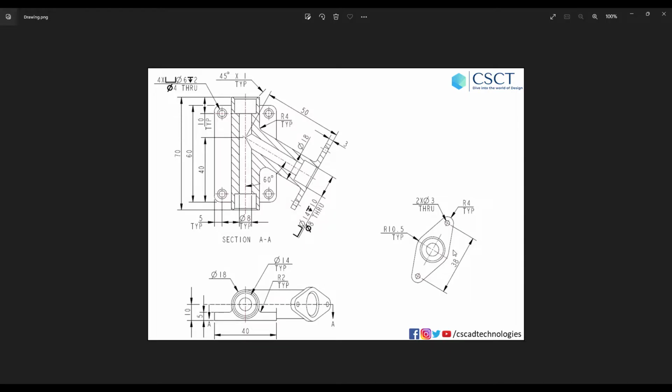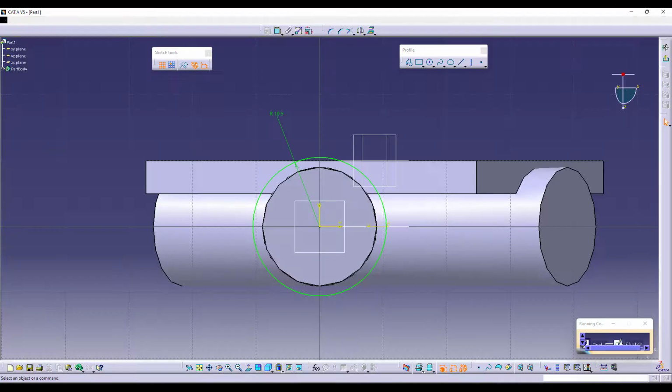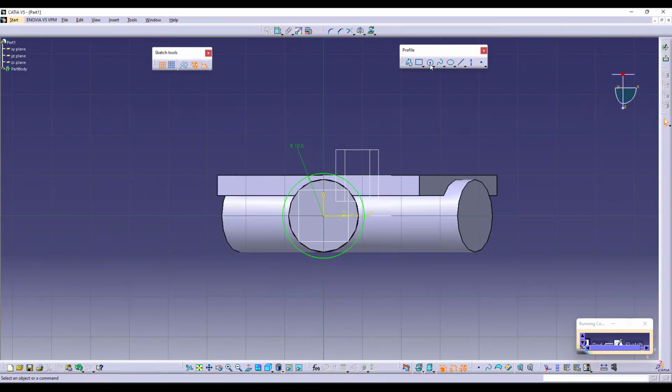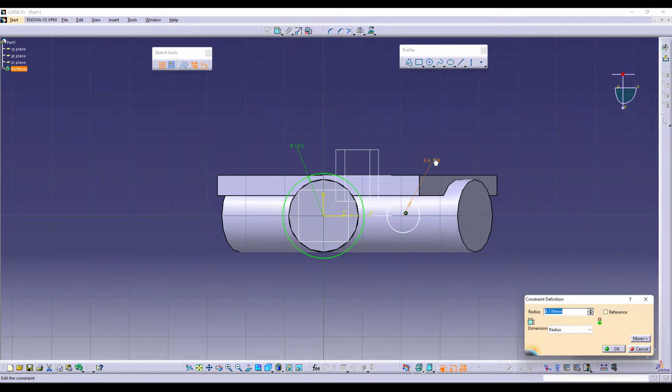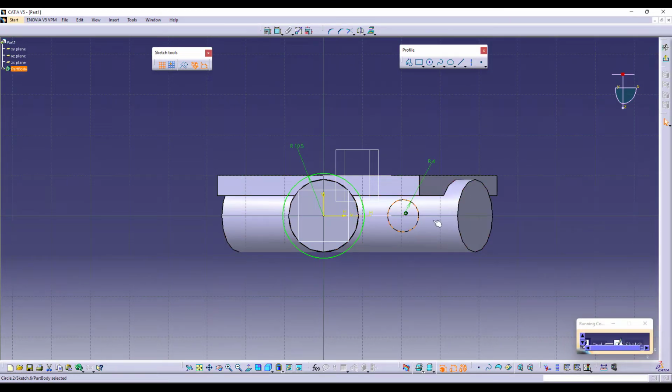Now, there are two other arcs as well at a distance of 38, which is R4. So let me try to take that too. It's in line with this, so it is already coincident in line with this, which is actually R4. You can mirror this onto the opposite side. If you do not have a vertical axis, use an infinite center line. Even that will help do so.